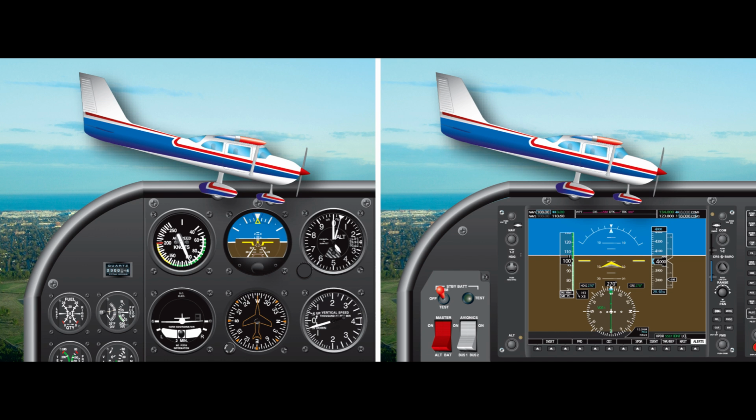2. Descent at minimum safe airspeed. A nose-high, power-assisted descent condition principally used for clearing obstacles during a landing approach to a short runway. The airspeed used for this descent condition is recommended by the AFM/POH and is normally no greater than 1.3 VSO. Some characteristics of the minimum safe airspeed descent are a steeper than normal descent angle, and the excessive power that may be required to produce acceleration at low airspeed should mushing and/or an excessive rate of descent be allowed to develop.